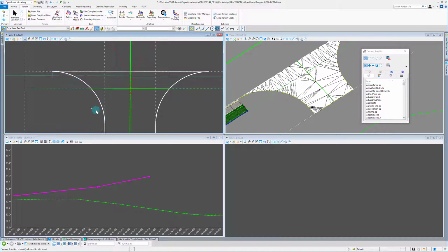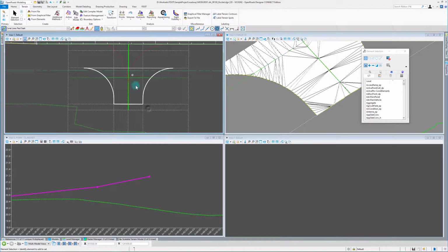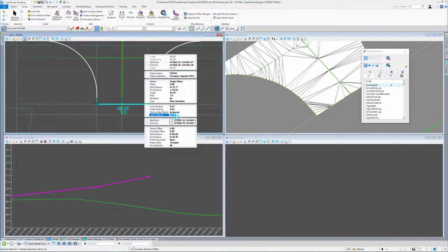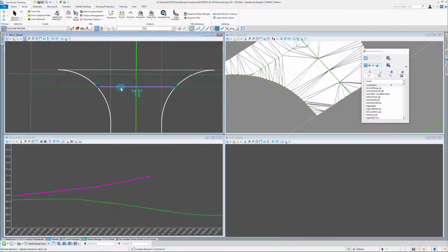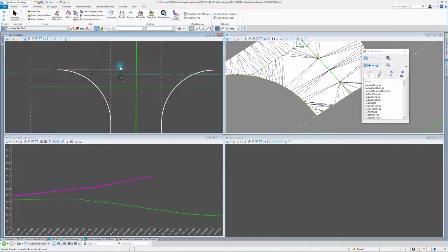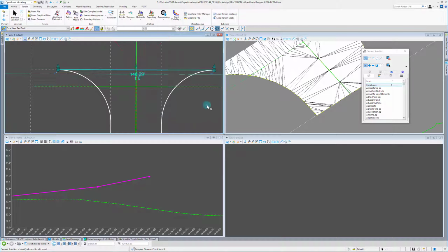So I like doing 2 on my curb returns. So you can see we have a lot more points now along that return. So we're going to do 2 over here. Let's think into the next step. So these ones that are parallel with the road, I like going with 5. We don't need quite as many as we're going parallel with the actual roadway. The roadway being our State Road 100 that we're building our road off of here. And then we can just do our last one here.